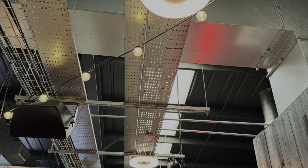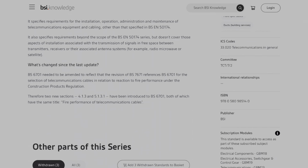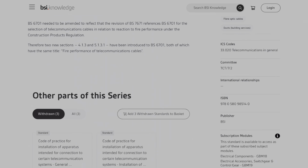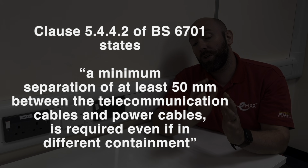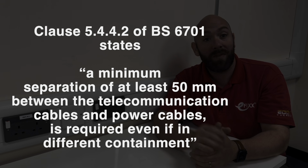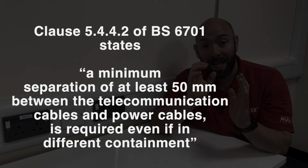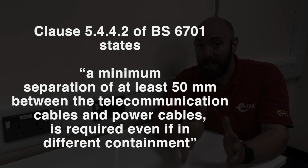Certainly if the band 1 cable is telecommunication, you will need to refer to BS 6701, which is referenced in BS 7671 110.1.3. Clause 5.4.4.2 of BS 6701 states that a minimum separation of at least 50 mm between the telecommunication cables and power cables is required, even if it is in a different containment.